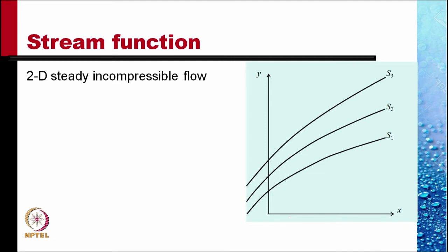Next, let us talk of another concept, the concept of stream function. A very important concept, a very useful concept. Let us study stream functions for only two-dimensional steady and incompressible flows, so that the equation of continuity, del Vx by del x plus del Vy by del y is equal to 0, applies.